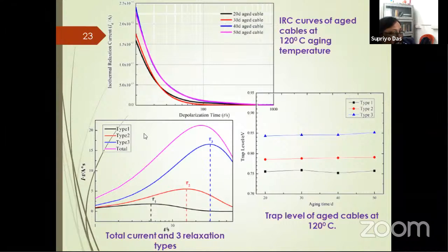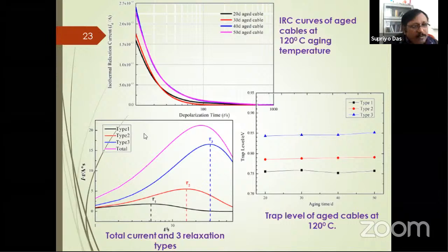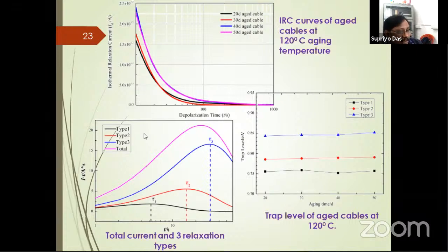So to understand these characteristics, definitely there is some form of aging, but we are not able to identify that aging, like 20 days aged and 30 days aged. So in order to understand whether some form of aging is there or not, this isothermal current, that is IT, the current into time versus log of T, is plotted.